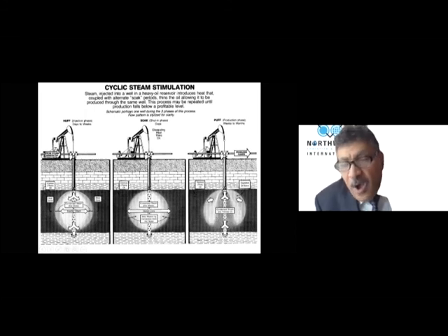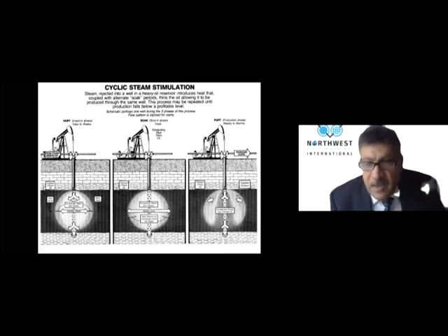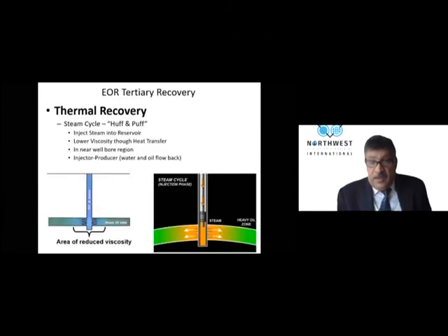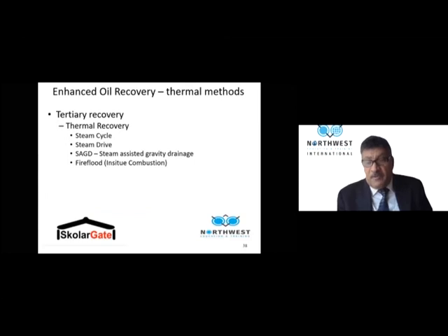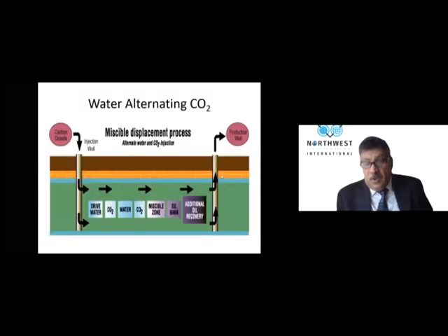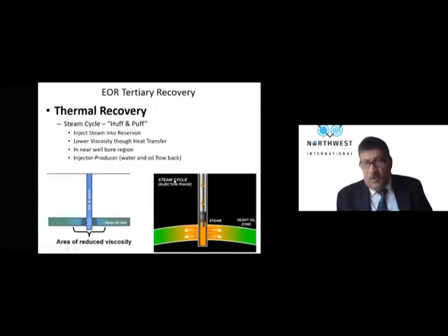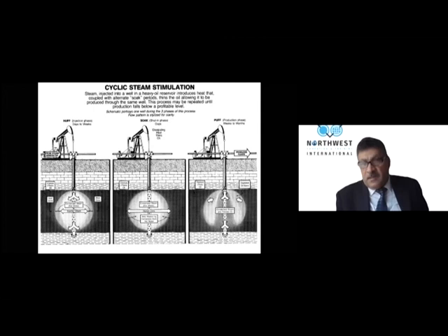It's only one well, the same well. You are doing the job in the same well. Here in CO2 flooding, as we have mentioned, you have 2 wells, an injector and a producer. In steam injection, no. Same well, one well, especially in steam cyclic. Remember that. Steam cyclic is in one well. The same well will be a producer and the same well will be injector.